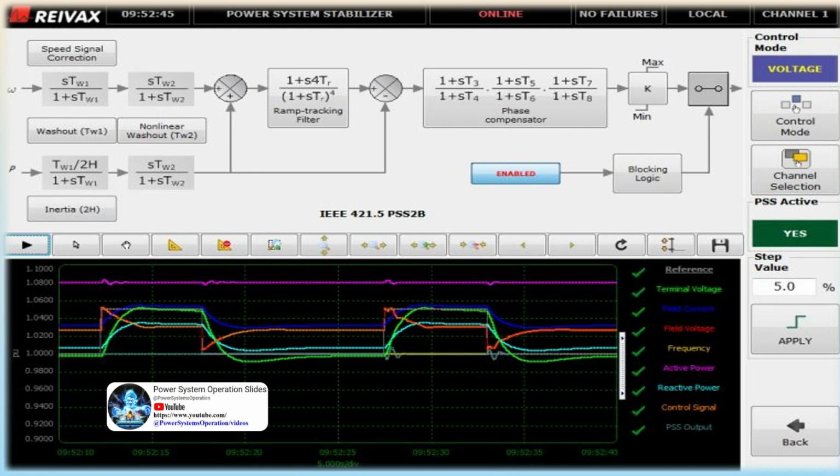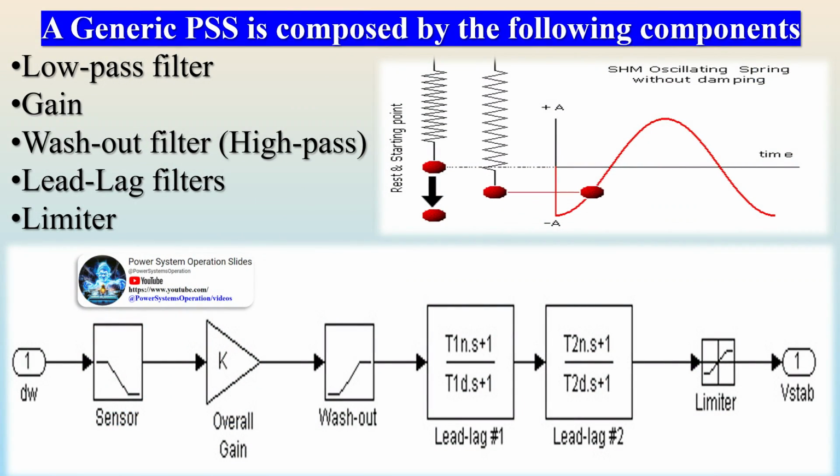While turning off a PSS can have significant impacts on the stability of a power system, there may be situations where it is necessary to do so. PSS performance is often evaluated based on its local mode damping. A properly tuned and well-performing PSS should provide sufficient damping to local mode oscillations. Frequency analysis can be used to determine the optimum PSS settings based on system characteristics. The PSS should be tuned to provide torque changes in phase with speed changes. Dynamic signal analyzers are commonly used to test the performance of AVR and PSS controls.